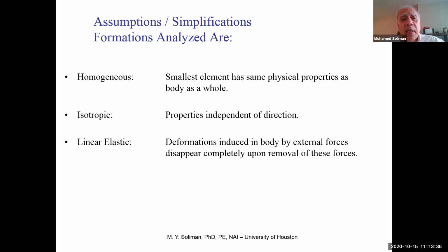Now, when you talk about rock mechanics, many times we make the assumption that the formation is linearly elastic. Basically, linearly elastic is as if you're looking at a spring. You push the spring down, you compress it, you relax, it goes back to its original shape. We'll describe it in a little more detail mathematically in a minute. But basically, all we're saying here is the formation will return to its original shape once you remove the external forces.